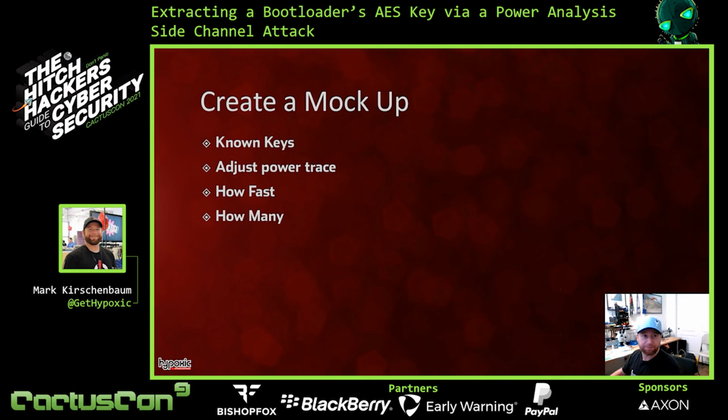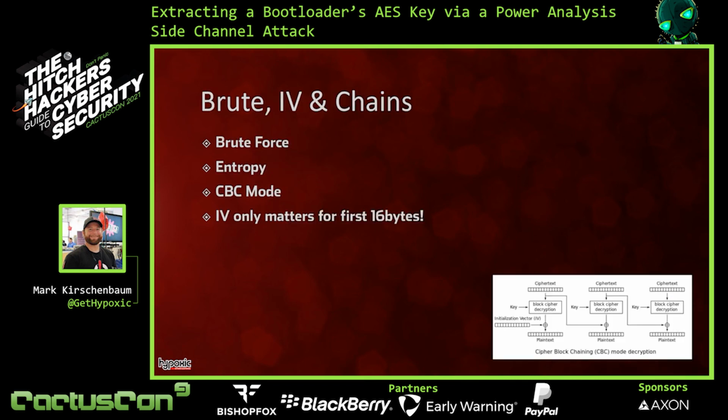When we're running these attacks, there are sometimes times when we can't extract a key for whatever reason, like a certain key byte won't be extractable. Well, luckily that now only becomes 256 possibilities I have to solve, right? That byte has only 256 possible numbers that it could be, and we just brute force that. We just pop that number into the round 10 key, work our way backwards to find the round 0 key, throw in the GoPro's update, decrypt it, and then throw it in an entropy kind of post-processor to see how the data looks.